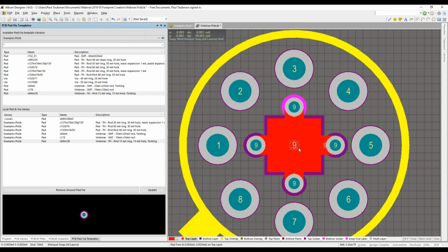And that will allow you to put a solder paste over here, which you're going to have to do anyways. You're going to have to put the paste down. You're going to put your part through it. They're going to put it through wave solder. It's going to melt this, and you'll have a better shot at actually making thermal conductivity between the bottom of your can to this over here.